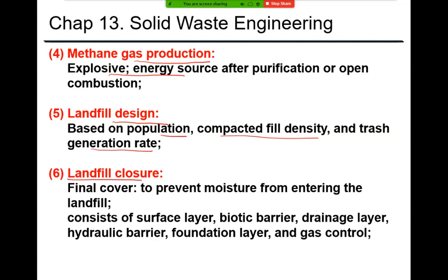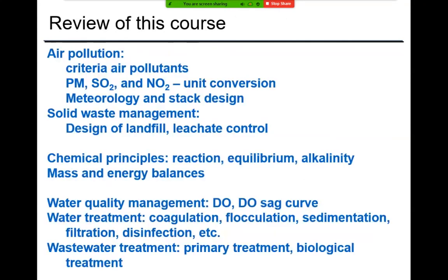So finally, when we close the landfill, when it's completely full, we can't just go away without treating the rest of it, right? We need to put on a final cover. So the final cover is to prevent the moisture from entering the landfill, because in that case, we're forming the leachate again. And then the final cover consists of surface layer, biotic barrier, and so on. Okay, so it's a quite complex design to prevent the formation of these liquid pollutants.